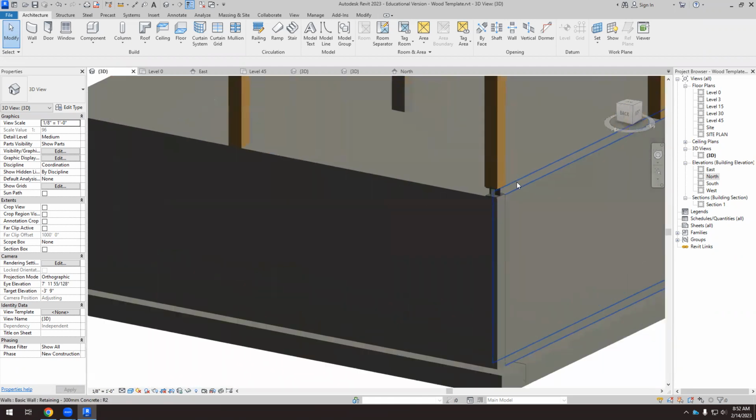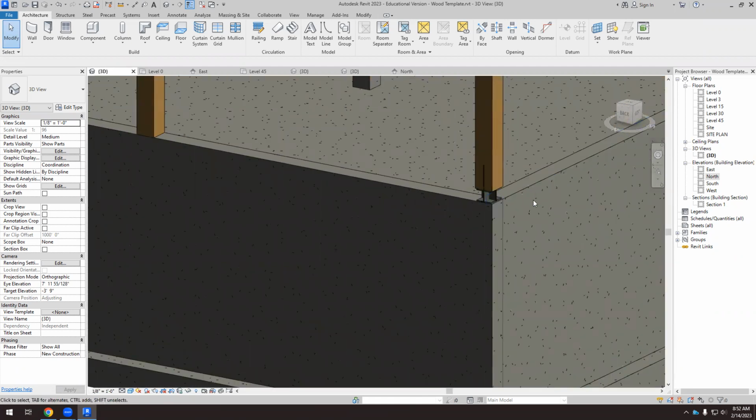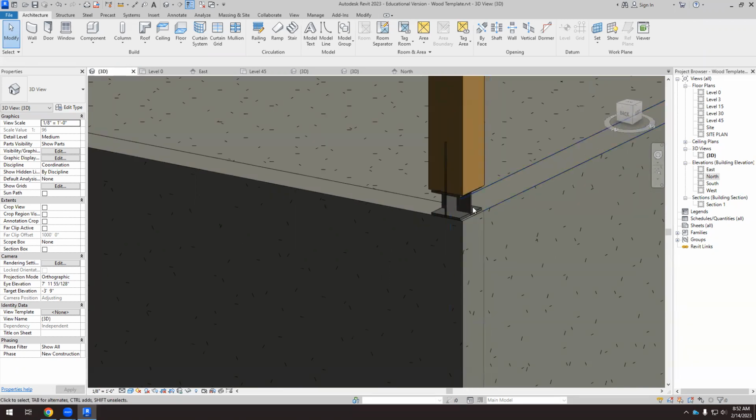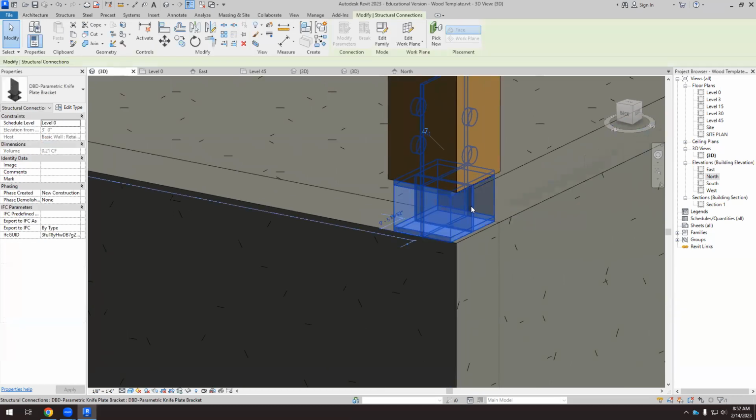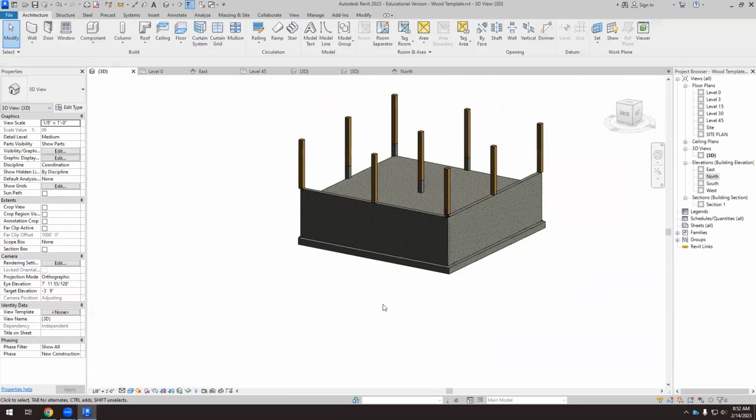And this is how it works when we're working with these kinds of structures. First, we need to prevent the wood from being in contact with the water, with the outdoor water, and especially with the soil. And then connecting the wood to the concrete, we always need a steel element just in the middle between the concrete and the wood element. Okay.